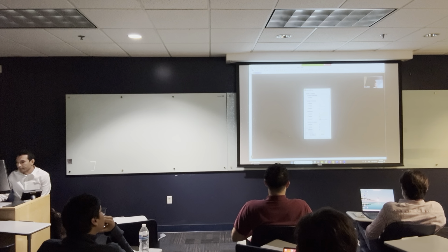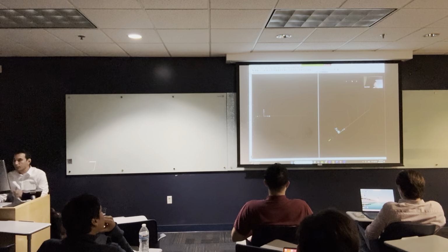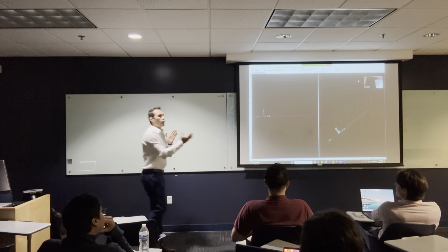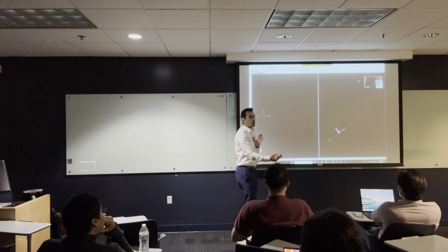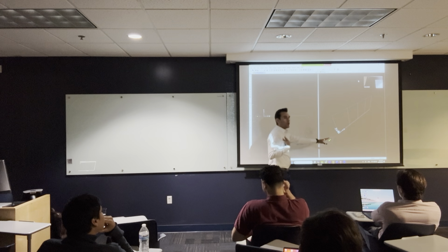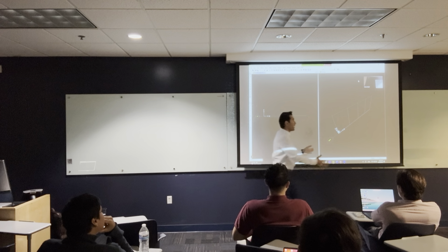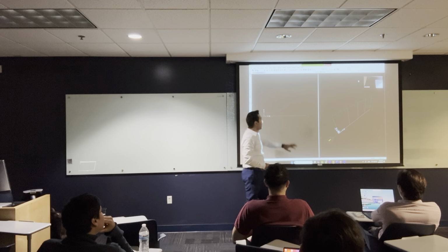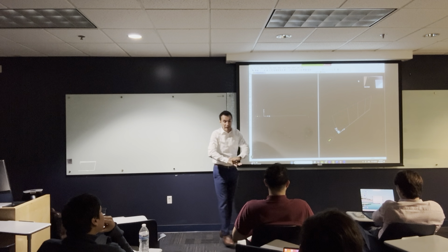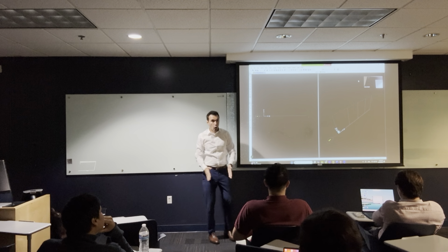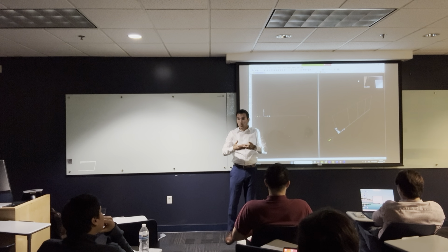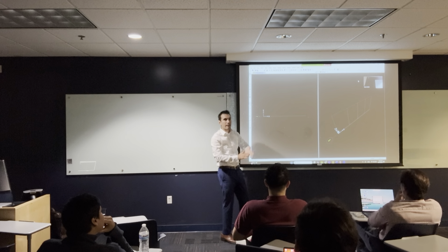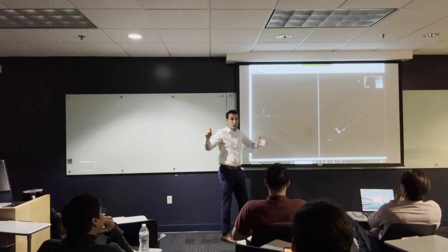Let's see what's going to happen. When I do this, SAP 2000 is going to divide the screen into 2 screens. If you want to make them one, you can, but I would rather work with 2 screens. I usually leave one as a 3D to see how my structure is evolving, and I make one a 2D, either XY if I'm working on a slab, or XZ if I'm working on a truss. So right now I want to draw my truss. XY is not going to help me, because I want an XZ so I can start drawing my truss.